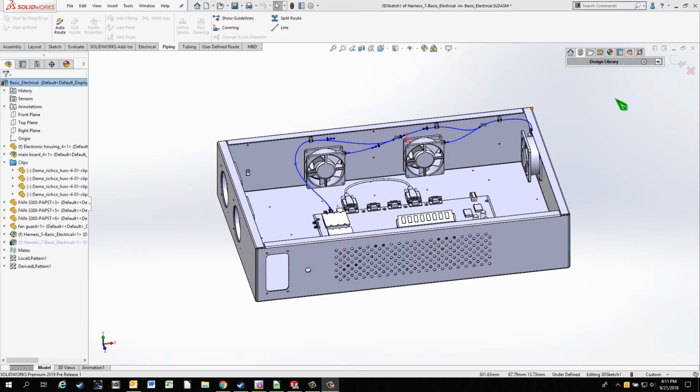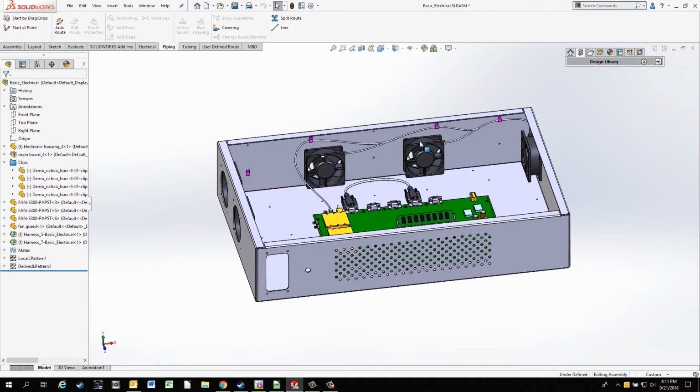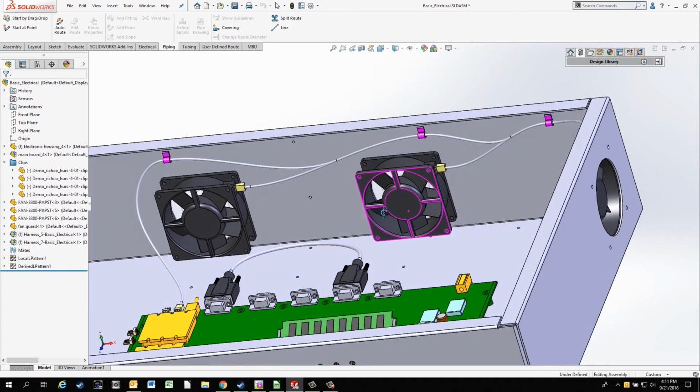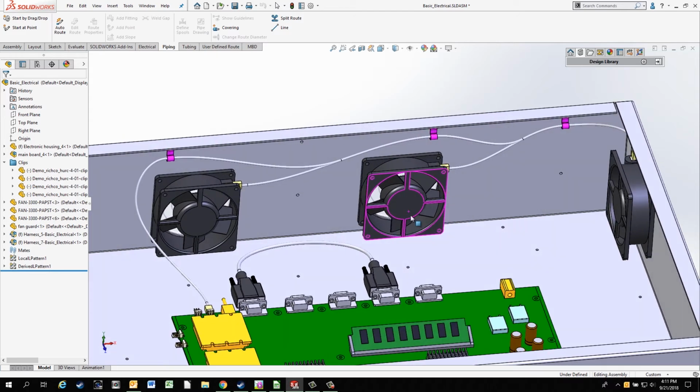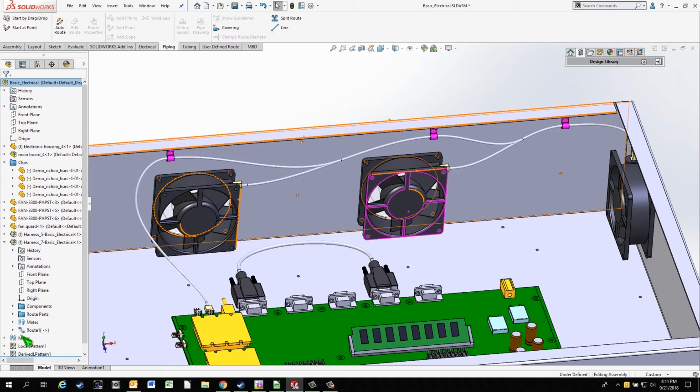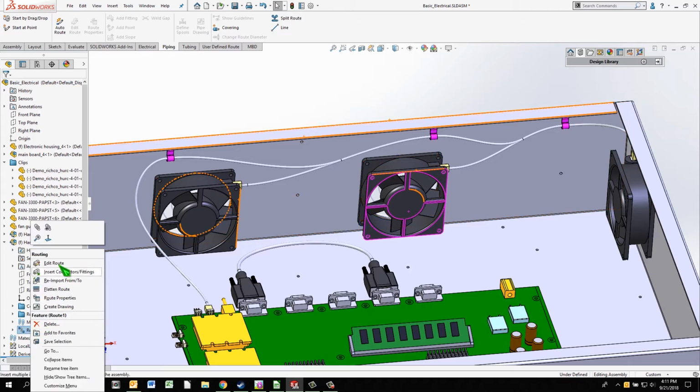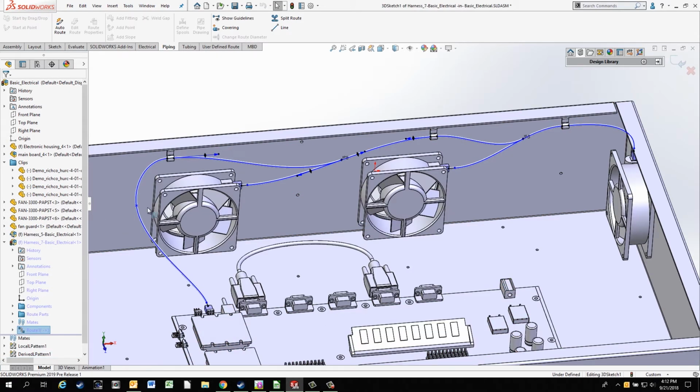The geometry looks good. If all we wanted was to create the model, we could quit right here. If we want to add electrical connection data, we can do that too. That command is known as edit wires, and we will need to be editing the route to access that command.